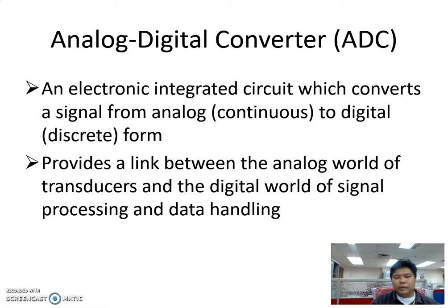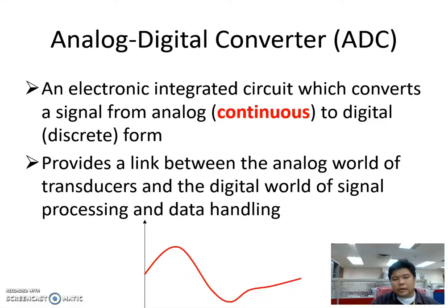It provides a link between the analog world of transducers and the digital world of signal processing and data handling. The main thing to remember is that the ADC changes the signal from an analog or continuous signal to a discrete form, so that your computer can understand the signal.